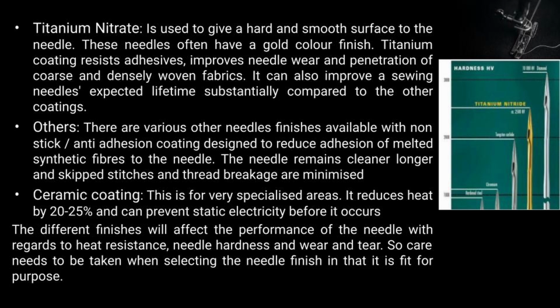There are more coatings. Let's talk about ceramic coating. This is for very specialized areas. It reduces heat by 20 to 25% and can prevent static electricity before it occurs. The different finishers will affect the performance of the needle with regards to heat resistance, needle hardness and wear and tear. So, care should be taken when selecting the needle finishing so that it fits the purpose of the garment or sewing stitch.